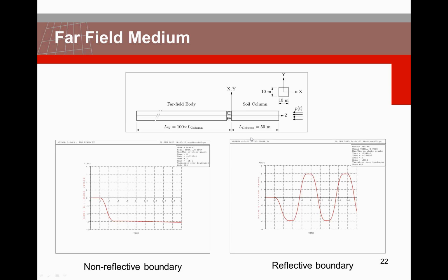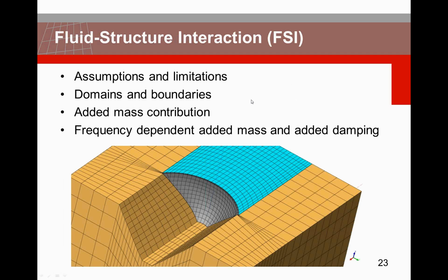So it is important to think about this and to decide based on some calculations whether you need those non-reflective boundary conditions or not. If you're in doubt, I would say use non-reflective boundary conditions, and only in specific cases where you know that there is no need to have them, then avoid them. But if you want to play it safe, just use them. We have the tools for it, so make sure you use them.